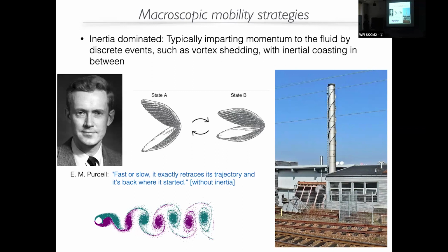One issue my civil engineers worry about, as I've learned, is matching of the frequency of the vortex shedding with some natural frequencies of the structure, like a bridge or a smokestack. So it's often desirable to minimize vortex shedding. And amusingly, in order to do that, you have to streamline the object. One way to streamline, of course, is to completely change its shape, but another way is to embellish your object with some kind of spiraling structure.